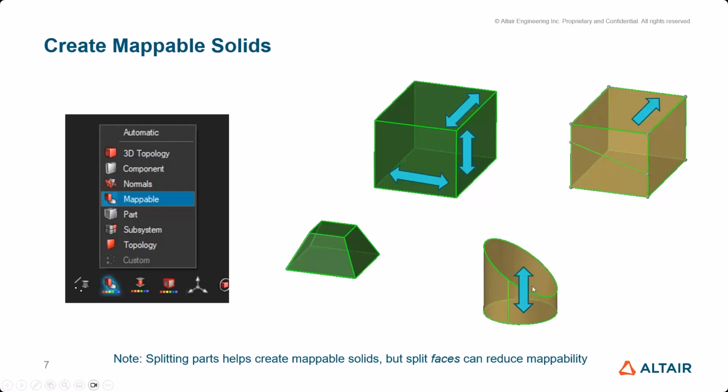In this case, you can put a mesh on either one of the circular faces of this truncated cylinder, and then extrude it through the length of the cylinder, but you can't put a mesh on the outer face and try to extrude towards the middle. That wouldn't work.